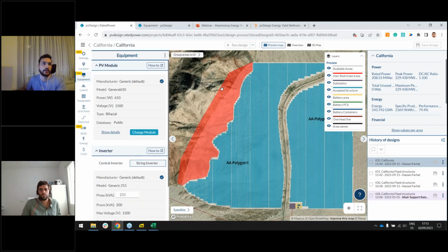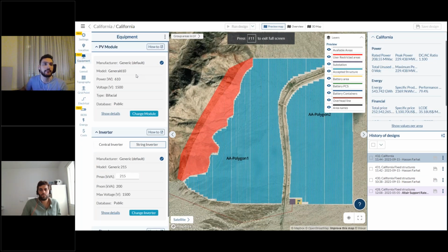Okay, with that out of the way, the next thing, also regarding these two specific equipment, is of course, you want to make sure you're setting the right plant size in both tools. And the two tools, PVsyst and pvDesign, don't exactly work the same way when it comes to this. For instance, pvDesign will automatically set the DC capacity based on the site that you have. In this case, I have this big site that we have in California, and pvDesign just automatically fills it in for me.